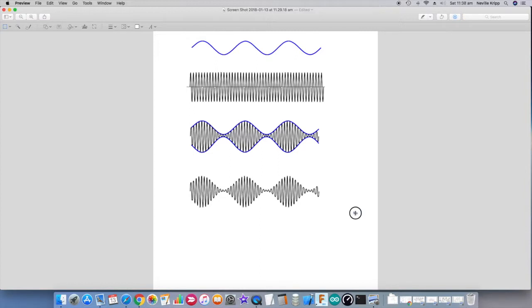So to recover that signal, first of all, we just half-wave rectify it. And you'll note that once it's half-wave rectified, if we were to smooth out the peaks of that particular waveform, we'd actually have that original waveform back again. And look, it's as simple as that. That is exactly what we do. We smooth it with a RC network, a capacitor and a resistor, and recover that original audio signal off the IF frequency. So in simple terms, that's all there is to AM modulation and demodulation. So let's take a look at the circuits now and see how it is in practice.